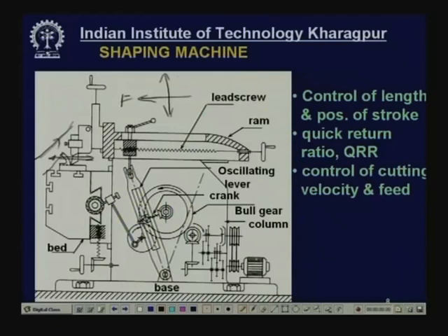Now, this motor rotates, and rotation and power go through the V belt into this shaft, through this clutch, into this cluster gears, and ultimately through this gearbox, called the speed gearbox, come into this space and then rotate this pinion with the help of this bevel gear. Now, this bevel gear rotates again this bull gear, this is called the bull gear, the large gear.